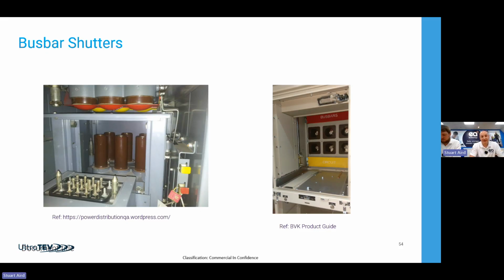If you've got high humidity, I think one of them was associated with the heaters not being on in the panel as well. So if you've got a bit of humidity and you've got this relatively short distance between the two, you can quite easily get a flashover between there, and you start getting partial discharge activity. So if you've got some panels in your switch room and the breakers racked down, but these are there, definitely always have a listen round with your ultrasonic microphone as a minimum, and take some TEV off the breaker still, even though it's not physically connected, just to make sure there's nothing major going on there.